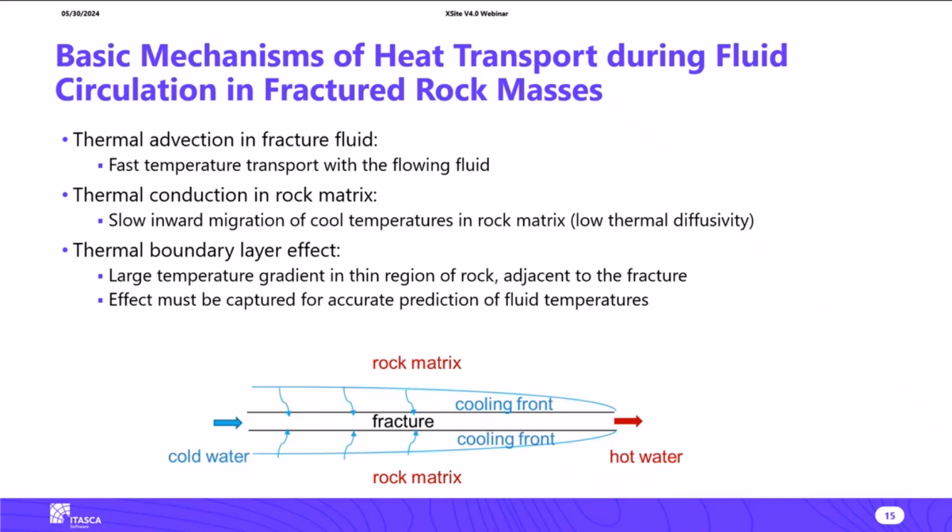On the other hand, stimulation of these reservoirs takes place for a much shorter time, approximately a couple of hours, or sometimes even shorter. However, if you are simulating fluid circulation, as we would do during heat production, in that case the entire process is driven by heat conduction.